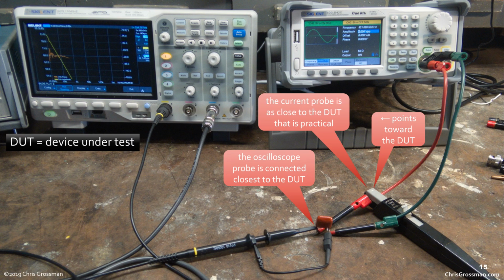The other thing you need to do is keep these leads coming out of the function generator short. If you make them longer, you can still get measurements, but the inductance in here is going to screw up your measurements at higher frequencies or reduce your dynamic range. So you really want to keep these short.